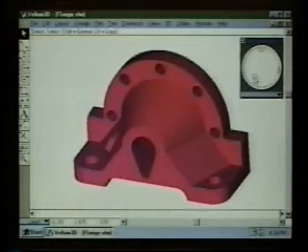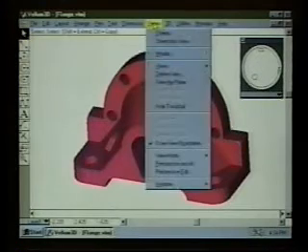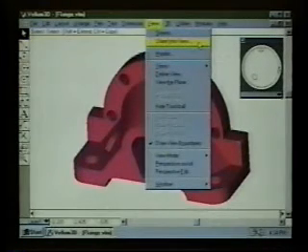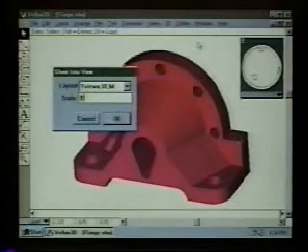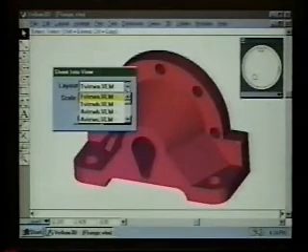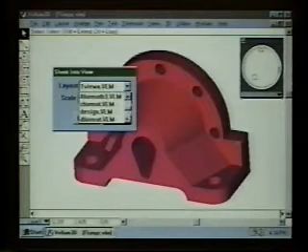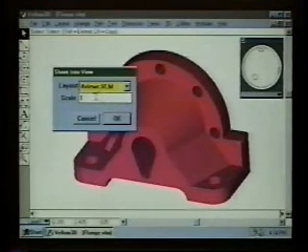The rest of the story goes on to say, well, now that I've got this part designed, I want to go on and do drafting with this. And so to get this thing into a drawing, we want to have a drawing format that has 4 views and title block and border and whatnot. And to do that, we pick a single command called Sheet into View. When you pick this command, you get a layout option, and you have a dialog box here with many different layout choices. And I'm going to pick the one here that's 4 views for a C-size drawing, and just leave the scale at 1. So this will have 4 views already set up on it, a C-size title block and border with the title with the detailed views, top, front, right, and isometric. When I say OK,